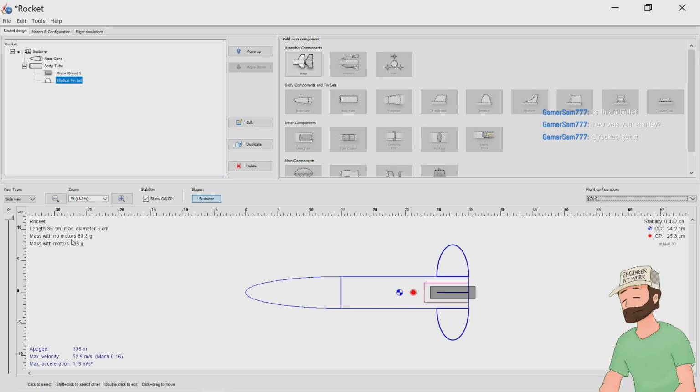One way, the best way to reduce how high we're going is to make the rocket fatter. And the best way to increase this is to make the rocket longer, and make these fins larger. The larger these fins are, the more correcting force they make when the rocket tilts.